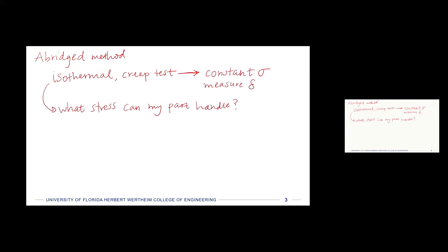Usually, this is what we're solving for because we can't control the creep strain at which these things eventually break. That's a material consideration. It is what it is. There's a creep rupture strain. That's the maximum we can have. And then we also usually need to design for a design life. I need it to last X amount of cycles. So these are either system configurations or material considerations that are unchanged.